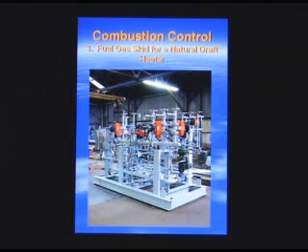Generally, the radiant sections of a fired heater, which you'll see a little bit further on, have a ceramic fiber refractory, which can allow flue gas to get behind it. However, there is a special asphalt coating that is put on the inside, which prevents the condensing gas from attacking the carbon steel. We'll see that in a little bit here.